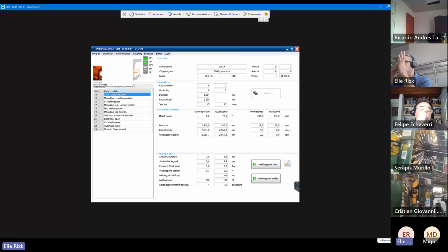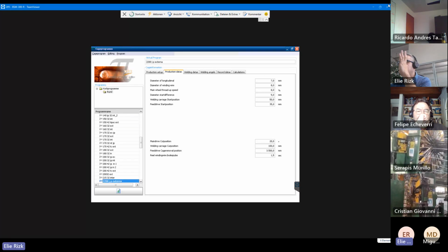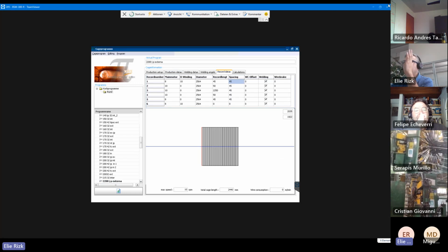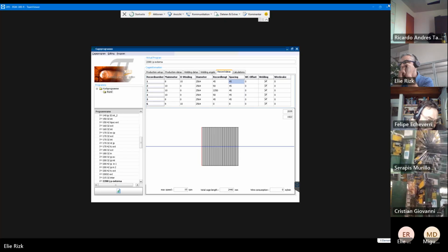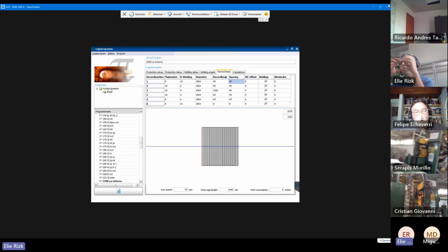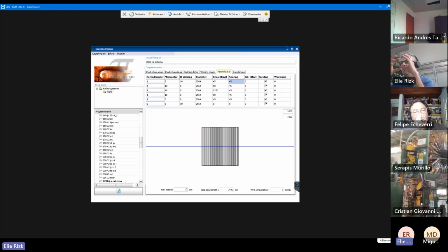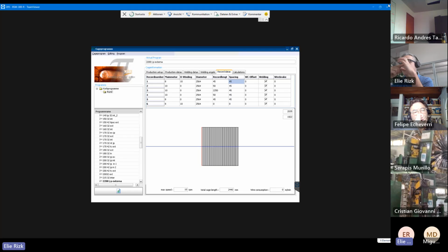When the feed wheel is in front of the main wheel, the clamping bars are opened, and then when he puts the wire inside, the wire should touch the end and should stay there. So it's not like he pushes it and then it touches and goes back. This can create a problem. He should make sure that it is always touching, because the clamps close before moving. So if the position of the wire inside the clamp is good, this problem should not happen.